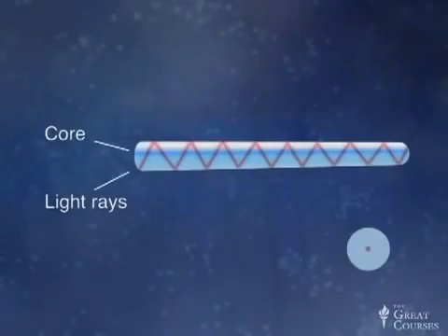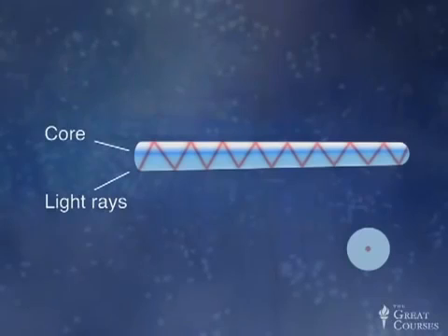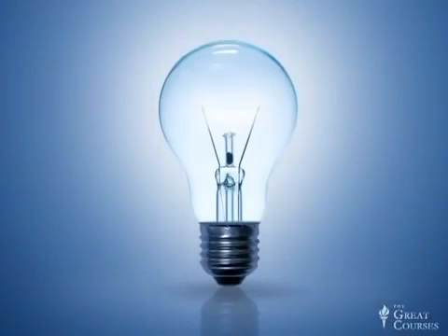These optical fibers, in order to achieve their single mode properties, in order to ensure there's only one available bounce angle, only one velocity for light, are quite small. They're about 10 micrometers in diameter. So they're not at the nanoscale; they're on the optical length scale. But in order to couple into these, we need to make a beam of light that's similarly small. So imagine taking a light bulb that puts light everywhere. It'd be very, very hard to focus much of that light inside. Even with a light-emitting diode, it'd be very difficult to couple most of the light into this very small aperture.